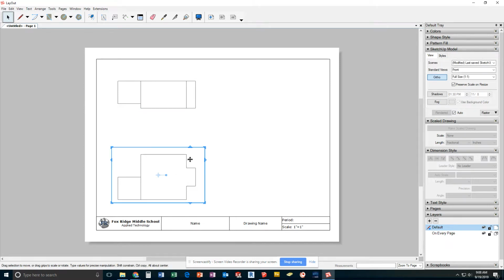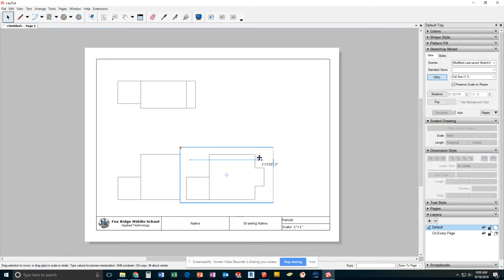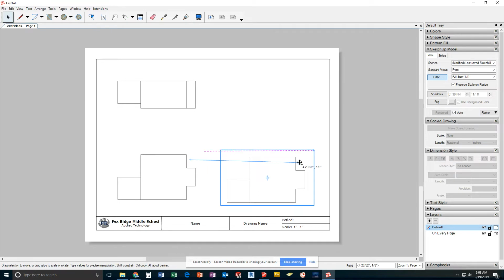I'm going to click this again, Control, click and hold both things, pull straight out to the side, do not pull at an angle, let go, change front in this drawing to right. So I have the top and the right side.